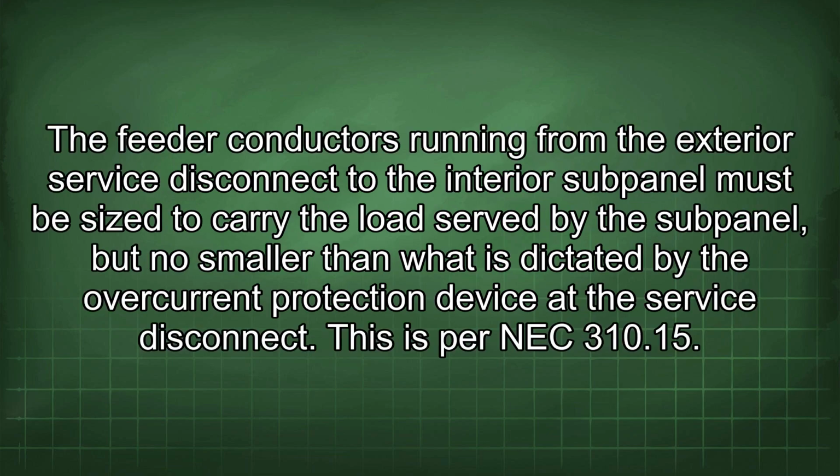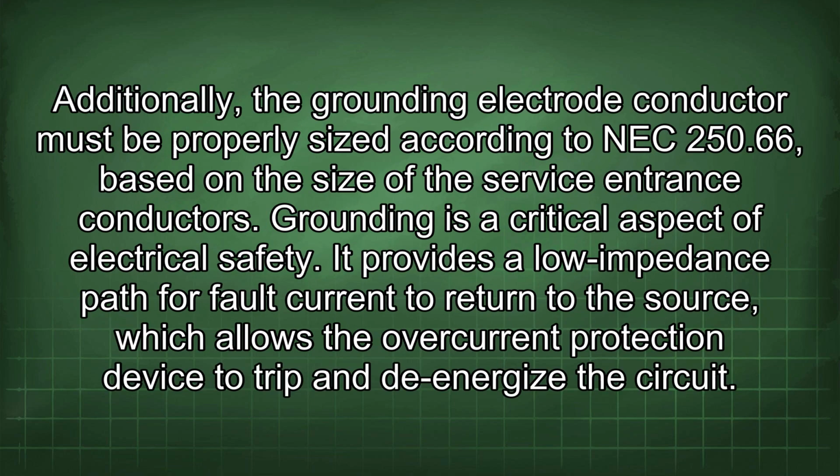The feeder conductors running from the exterior service disconnect to the interior subpanel must be sized to carry the load served by the subpanel, but no smaller than what is dictated by the overcurrent protection device at the service disconnect. This is per NEC 310.15. Additionally, the grounding electrode conductor must be properly sized according to NEC 250.66 based on the size of the service entrance conductors.